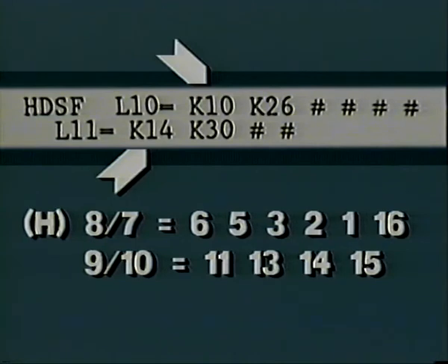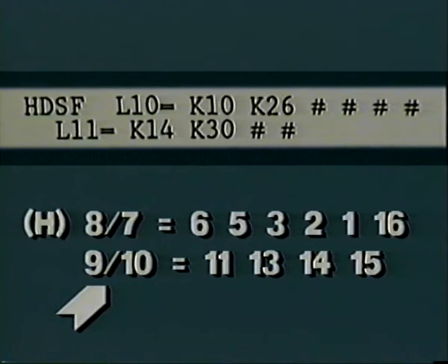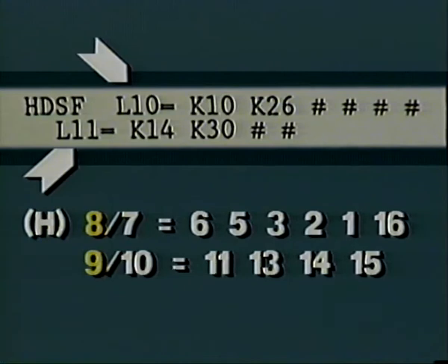Terms K10 and K14 correspond to pin numbers 6 and 11. This forced 1 corresponds to pin number 14. Also, notice how the pinout equation has 2 output pin numbers. The 2 pin numbers are for the true and false output terms. The true output pin will always be given first. If we apply this to our example, the output term L10 can be found on pin 8. The output term L11 can be found on pin 9.